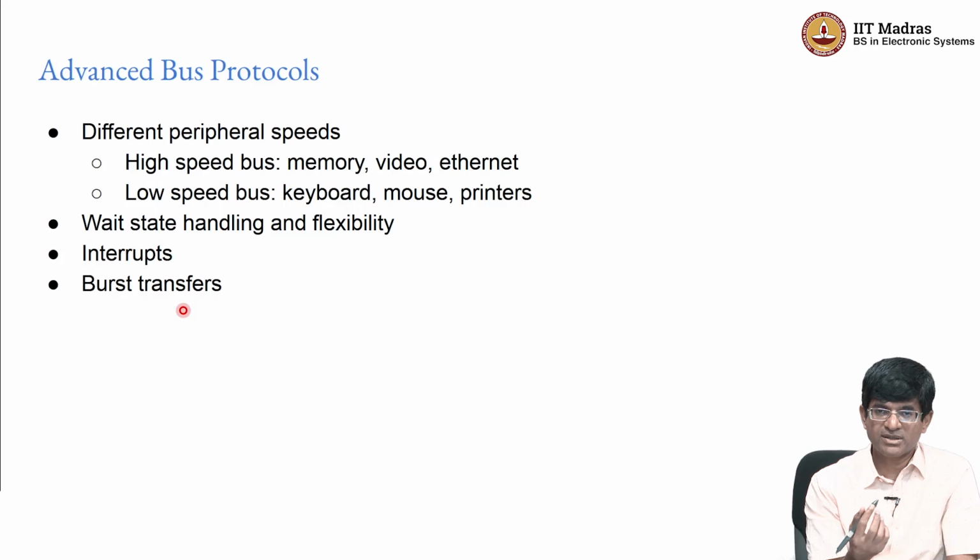There are of course certain kinds of peripherals in most microcontroller systems that do precisely this. This is exactly what DMA, direct memory access, handles. Now, in such cases, it can also simplify things further and say that rather than taking individual elements one by one, reading them from one place and writing them somewhere else, let me just issue what's called a burst transfer.